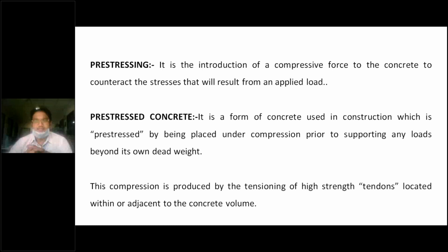Okay, so in that concrete itself there will be high strength tendons which you are going to pull, so it will create compression in the concrete. Then the concrete will be subjected to a huge compression force. That is the reason why in pre-stressing you are supposed to use high strength concrete to take care of high compression forces, and high strength steel to take care of high tensile forces. These are the two important points we have to remember while going for pre-stressing technology.